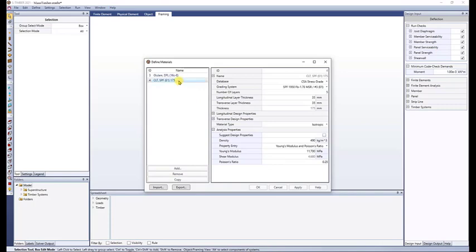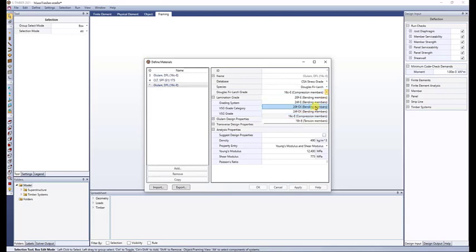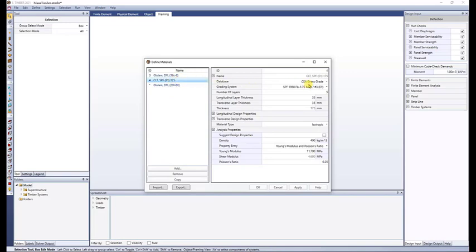button. Since I require 2 different sets of glulam material, I just click on it and then create a copy. And I can start changing the properties here. So this will be 20F AX. And if required, you can also modify this, but we will just keep the defaults for this material. As for the CLT, I just need to change the number of layers set to 7. So now it has a thickness of 245 millimeters. I click Apply, and then OK.